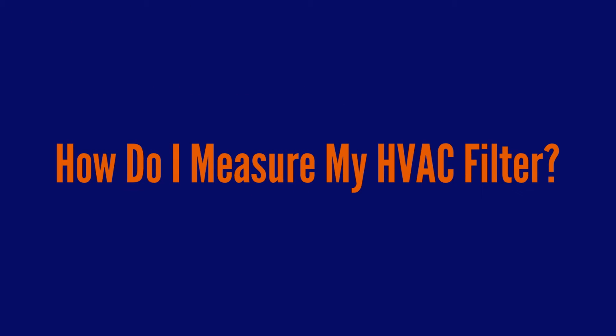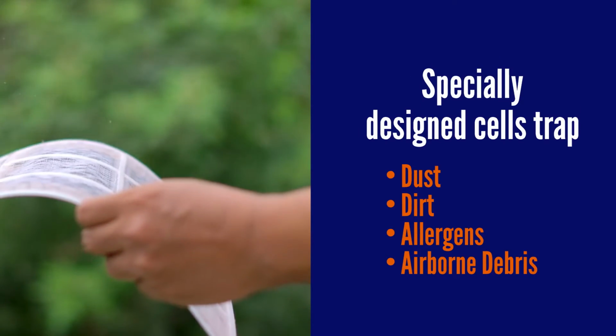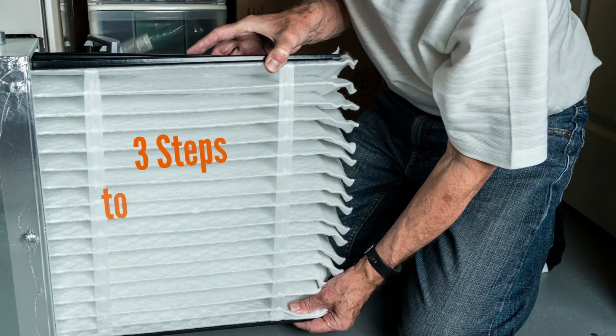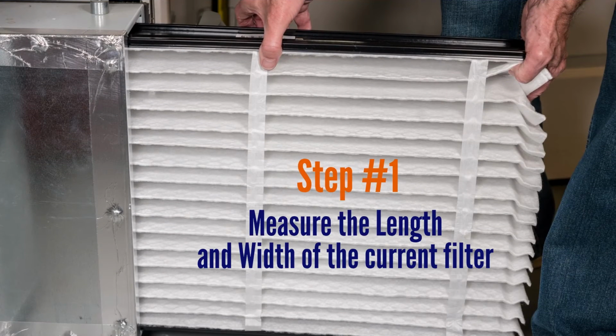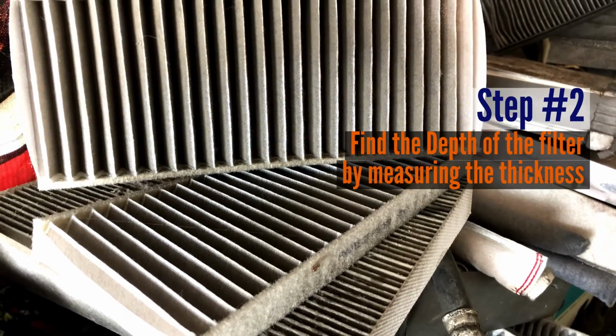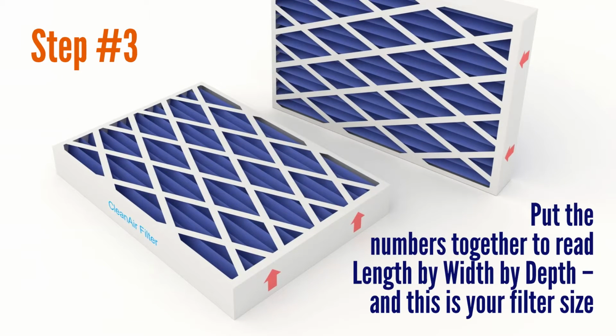HVAC filters come in a variety of shapes, sizes, and materials. Their specially designed cells trap dust, dirt, allergens, and other airborne debris, thus keeping it from circulating through the rest of your home. Therefore, when it comes time to change a filter, it is important to use the correct size for your system by following these 3 simple steps. Step number 1, measure the length and width of the current filter. Step number 2, find the depth of the filter by measuring the thickness. And finally, step number 3, put the numbers together to read length by width by depth, and this is your filter size.